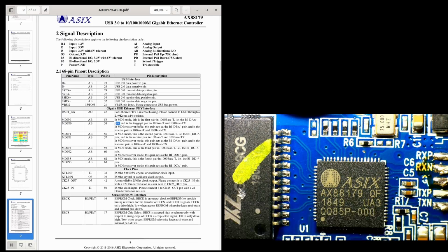And for transmit, for the 10BASE-T, which is of interest for us, and also for the 100BASE-TX, which we will evaluate in another video, this is the transmit pair. So MDIX 0 is the transmit pair. And then let's have a look. Okay, the second pair is for 10BASE-T something else, and for 10 and 100, it is the receive pair.